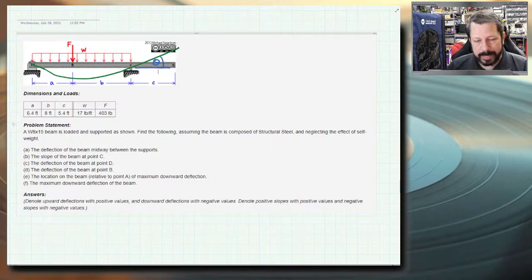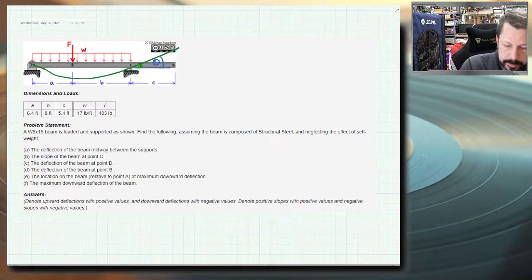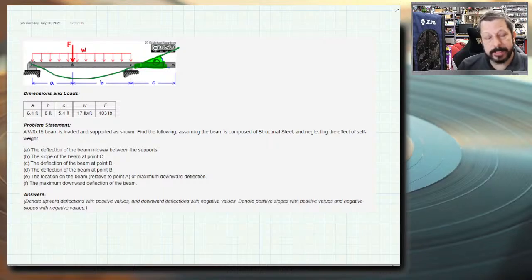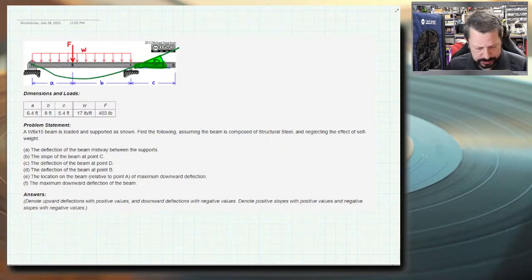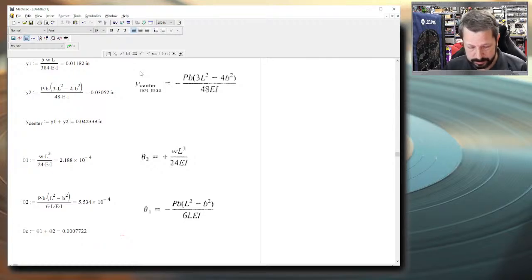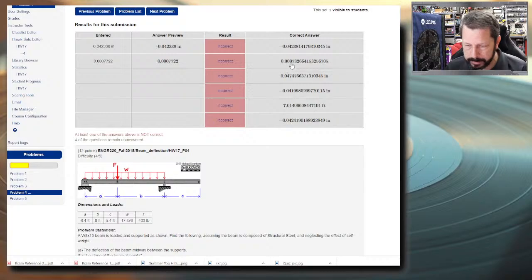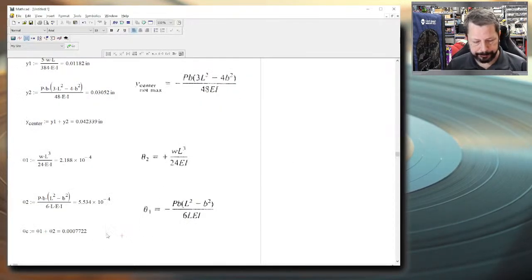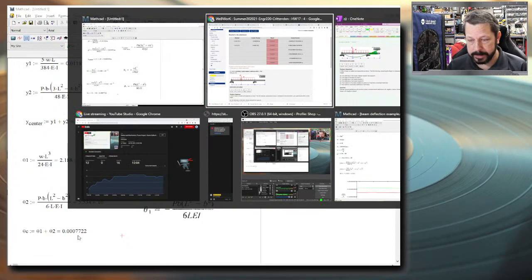All right, deflection of the beam at point D. So that's this beam. We've kind of done that before. That is where you take the slope at C. So we take this angle that we've got, and we assume it's a small angle, which it was, whether we were correct or WebWork was correct. It's a small, 0.007 radians. No, 0.007. Oh wait, is that a problem? No, they had 3 zeros. Super tiny degrees, or radians in this case.